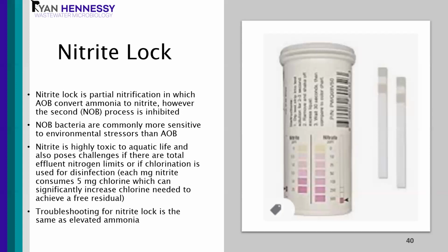So basically, generally you don't want to see next to anything for nitrite. And if you do have measurable nitrite, it's usually a sign that there's something wrong with your NOB bacteria.